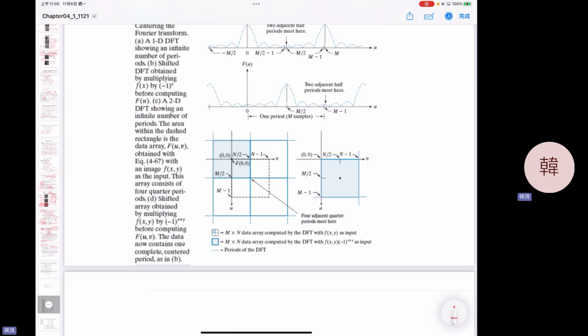You see the sinc stops at a certain range and point, and you pad zeros there. But mathematically, there's a discontinuity at the boundary point, and then you do the Fourier transform. So you cannot expect an ideal low-pass filter there, unfortunately, especially when you have a discontinuous boundary in your spatial domain.